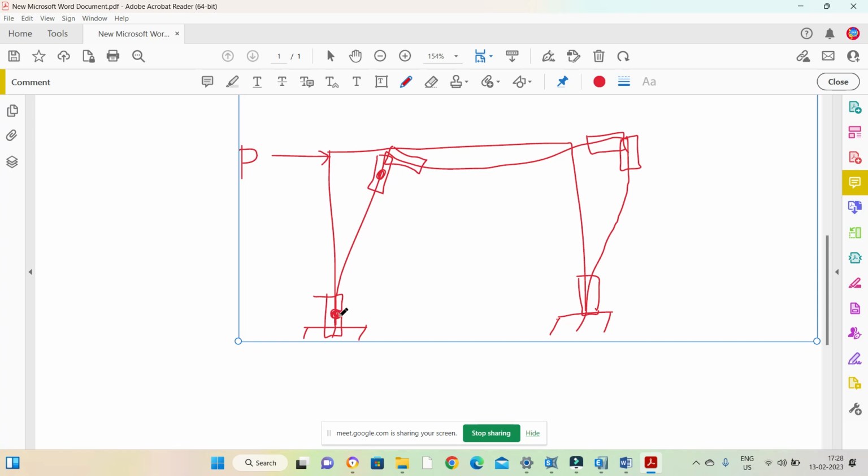So like this point where I have shown these dots, these points are called hinge points. It means there we are defining the hinge. It means here only we are assuming that the structure is going to fail. Similarly for this beam we will define hinge here and here, and for this here and here. And this is called concentrated plasticity definition.